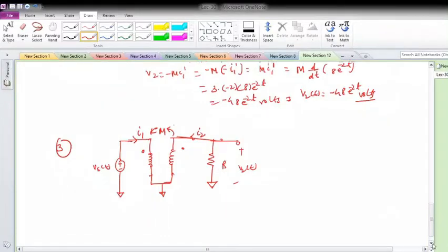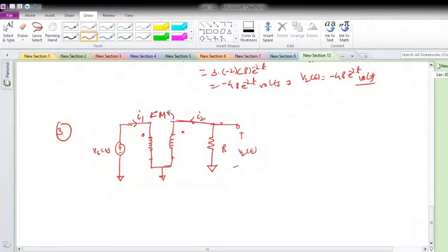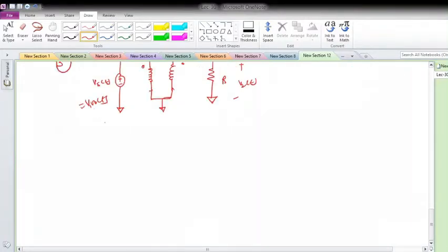Okay, so it is simple, and Vs is some constant, any number you can put, V volts or V1 volts or whatever it is. So first write for the primary, what was the equation? V1(t) is equal to L1 di1/dt plus mutual inductance M di2/dt. What was it for V2(t)? It is L2 di2/dt plus M di1/dt.